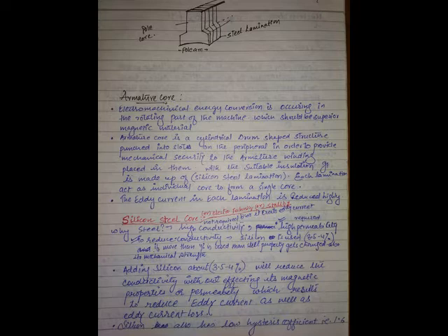What is the voltage across these 3 conductors in series? 3 volts. Total is 3 volts. If you connect all these 3 in parallel, what is the voltage? 1 volt. So armature winding is all the conductors in series.